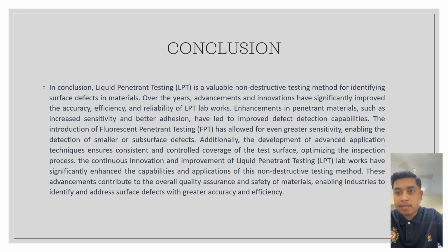Enhancements in penetrant materials such as increased sensitivity and better adhesion have led to improved defect detection capabilities. The introduction of fluorescent penetrant testing has allowed for even greater sensitivity, enabling the detection of smaller or subsurface defects. Additionally, the development of advanced application techniques ensures consistent and controlled coverage of the test surface.